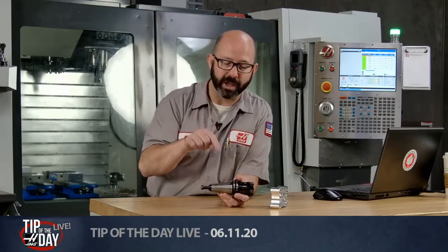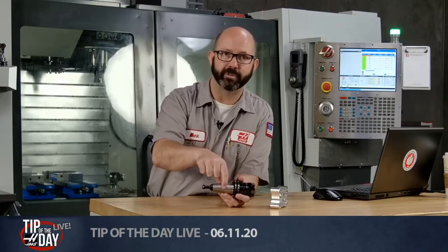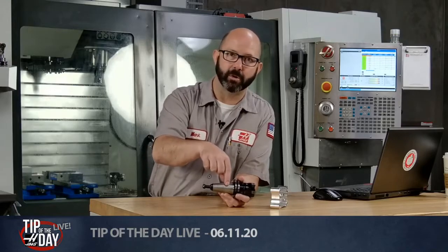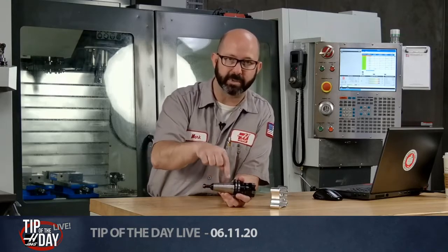Now, do not probe the Z until after you've found the Z, the Y-axis center line. Otherwise, you won't be probing the very top of the part. You'll be probing something other than zenith. You'll be off center. So always probe the Y web first, beep, beep, beep.